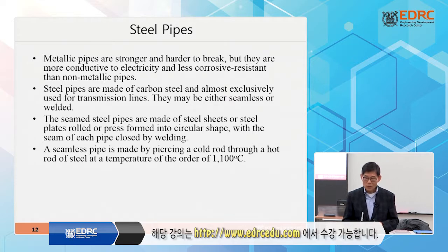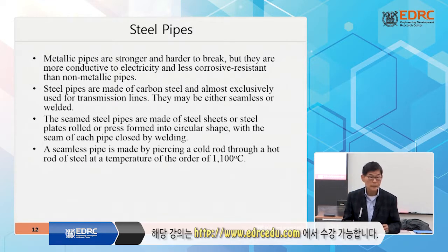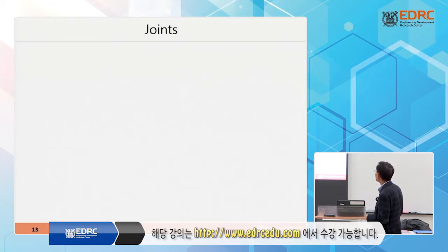Up to now, all transmission pipelines, since they operate at higher pressure, 800 or 900 psi, about 5,000-6,000 kPa to even higher than about 10,000, even 14,000 kPa range, so plastic pipe is not applicable here. So all steel.